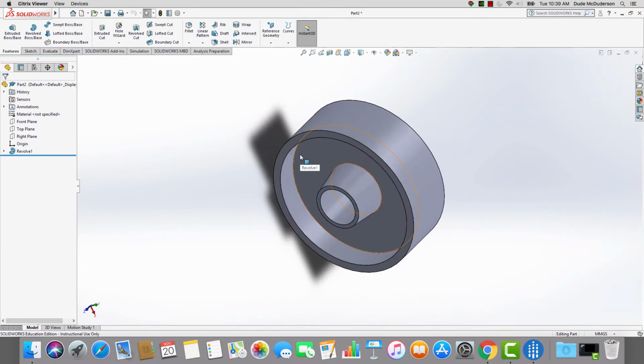There's one last detail I want to add to this, and that is rarely will you see really hard edges on things. Typically when you manufacture, you add what are called fillets or chamfers, both to ease molding processes as well as to relieve potential areas of stress concentration, like at this corner here. Adding fillets in SolidWorks is really easy to do. Up here, we haven't really used the modify tools yet, but we're going to choose this first one called fillet.